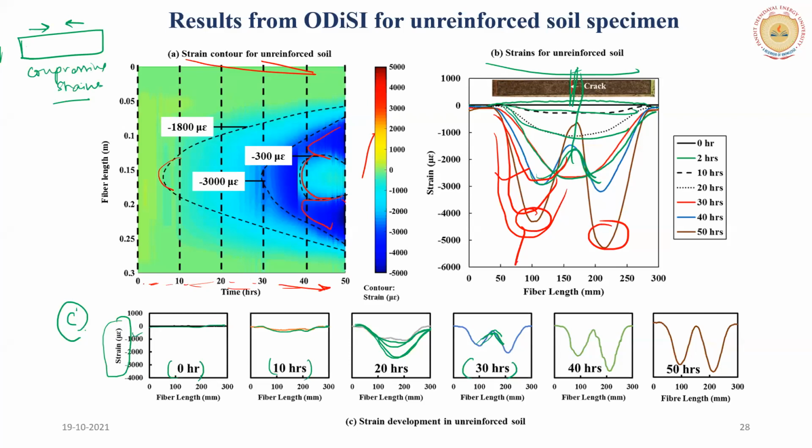We have a jacket on top of it, because the strains are even higher if there is some deflection or large amount of strain. Different types of jackets come up, and there have been some studies discussing how much the coating or the jacket changes the strain value.